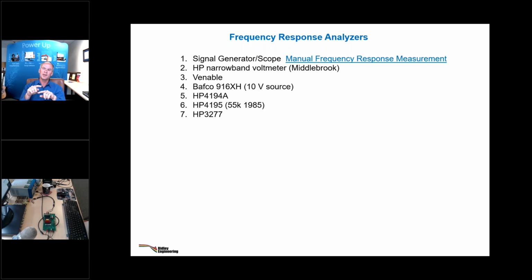You put the meter at the difference between the two. So now you're measuring 1, 2, 3, you're triangulating. And this is actually a very accurate way of measuring the phase between two signals. They can be very distorted, but it will pull out the fundamental, and it will measure the phase shift between them by using the cosine rule and the three measurements on the triangle.